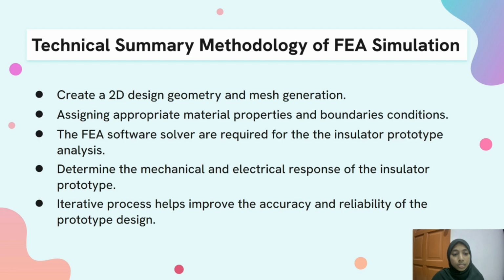The third is the FEA software solver required for the insulator prototype analysis. A structural problem solver, such as one that can handle static or dynamic analysis, is chosen for mechanical analysis. A solver that can resolve electrical field equations is chosen for electrostatics.